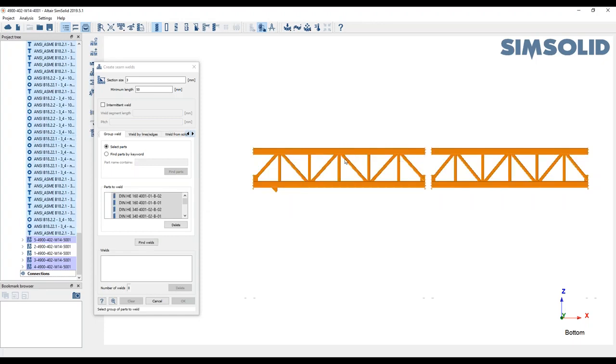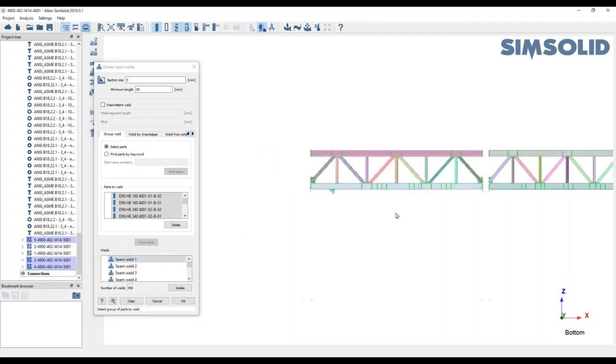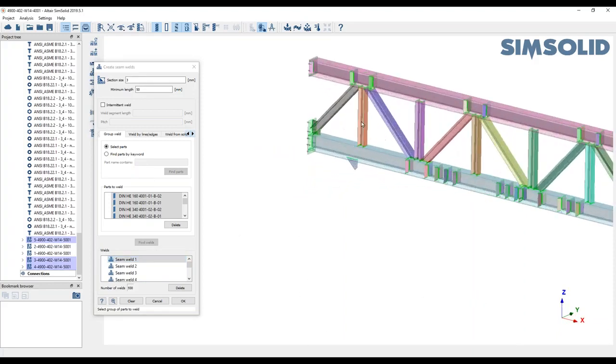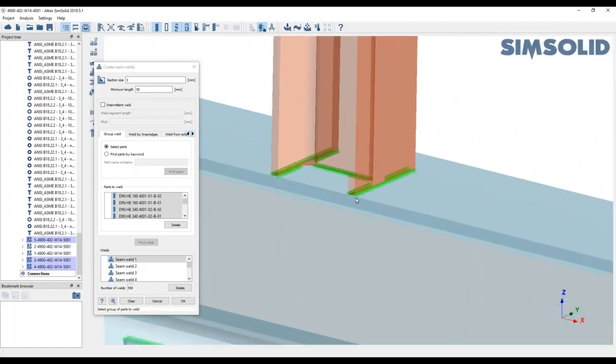Now, because the two sub-assemblies are not connected, it's going to weld this sub-assembly and weld this sub-assembly. So if I find the welds, this is a bit like having automatic contacts inside, let's say, Nastran, but the beauty here is that it's a solid plate and it's going to create contacts on either side of the plates. Which is a pretty tedious task inside Inventor Stress or even Nastran, because if I zoom into an area, let's take this example here, can you see what happens?